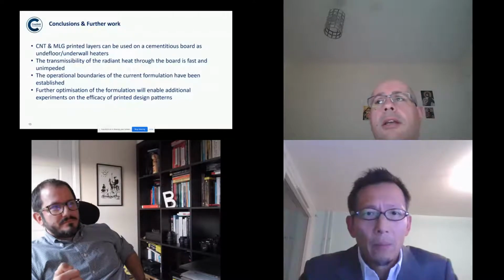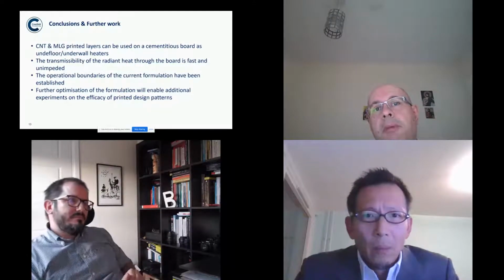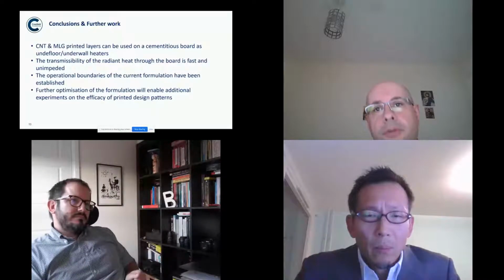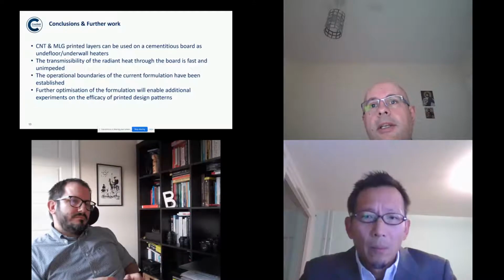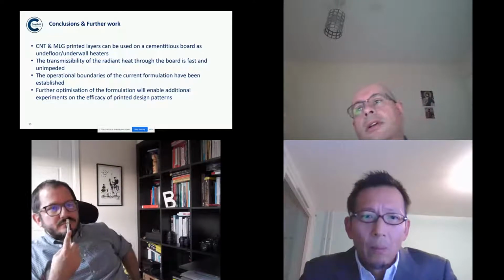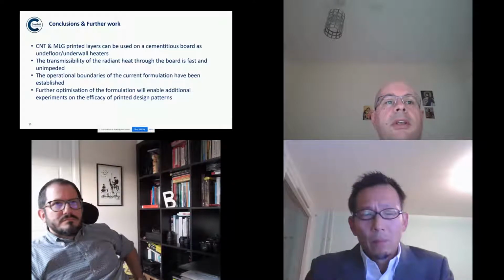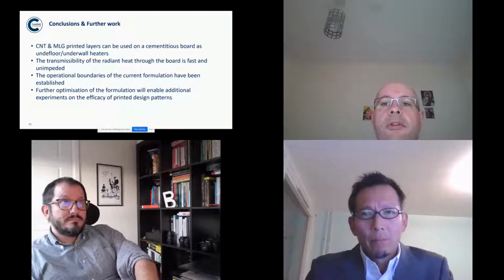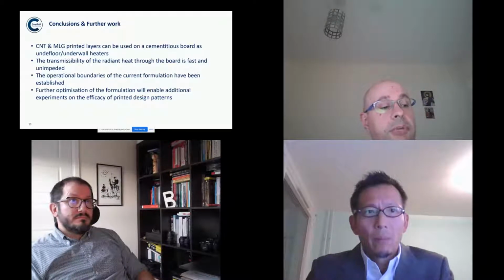Usually there would be an impermeable moisture membrane before you lay down such a substrate, either on the wall. You can have Tyvek type of materials preventing moisture ingress, or you would have other types of moisture membranes.